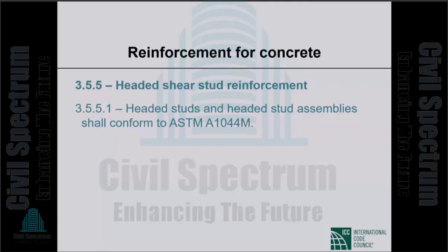Also, there is no local thickening of the slab on top of the columns. Those thickenings are called drop panels. Further, there are no column capitals. The column tops are not flared to give us a larger column area at the top. So it is a slab supported directly on columns without any drop panels or column capitals.